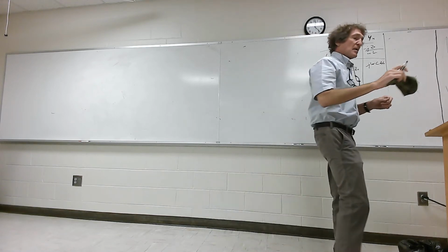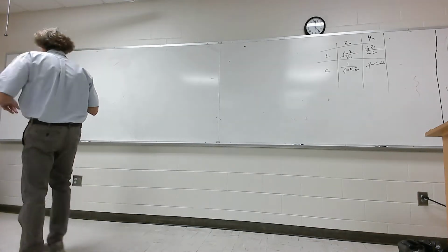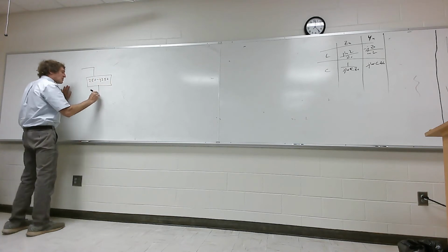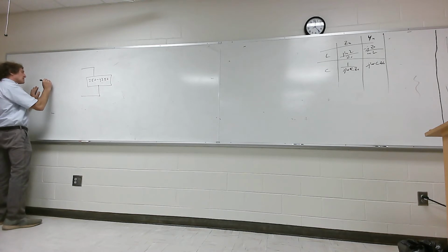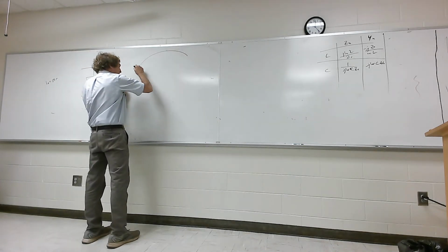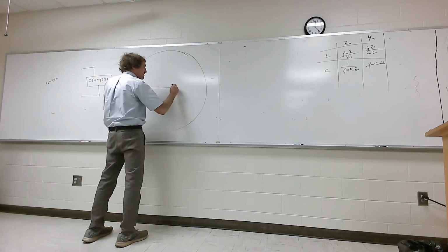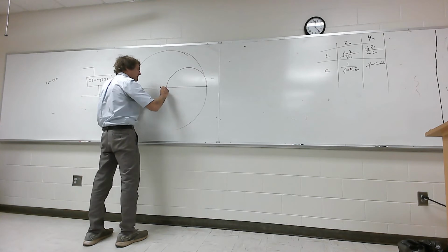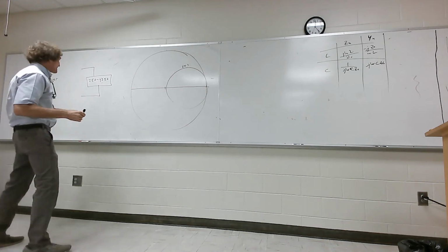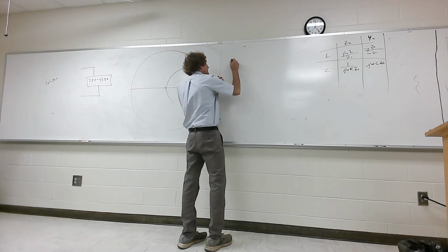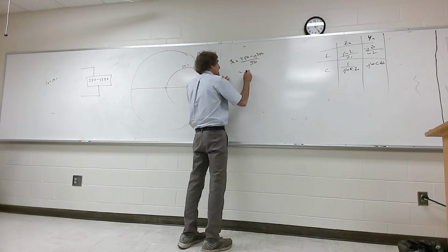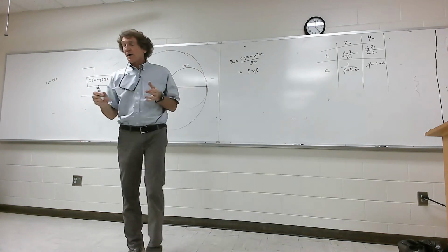So this one, we have a load of 250 minus j250. Yeah. So, 250 minus j250 is the load, and the characteristic impedance we have over here is 50 ohms. Okay. It's going to be a tight circle to see. So now I'm going to freehand this, and you can follow along in the book or not. First thing I have to do is normalize this. So my ZL is 250, Z naught is 50. So I find normalized ZL: 250 minus j250 over 50. Well, that's 5 minus j5, correct? All right, now we plot that.